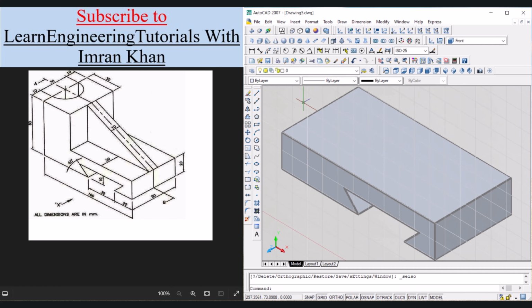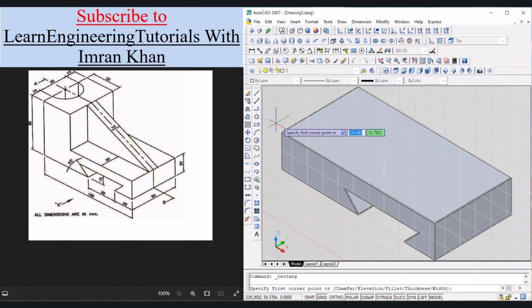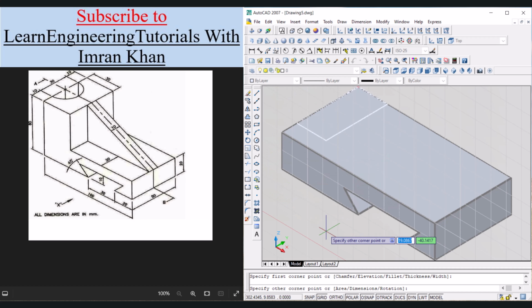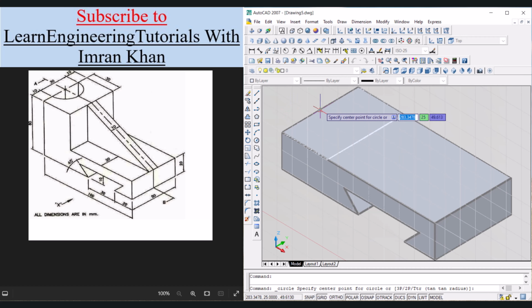Now we have to draw a rectangle over here in the top view, so click on top from the UCS option, click on rectangle icon, click on this corner, and now in this view we have to draw a rectangle, and the dimension should be 30, tab minus 50, enter. Again we have to draw a circle, so click on circle, click on this midpoint and write the value of 15 because the 30 dimension is written over here, which is diameter. So we have to write 15, enter.